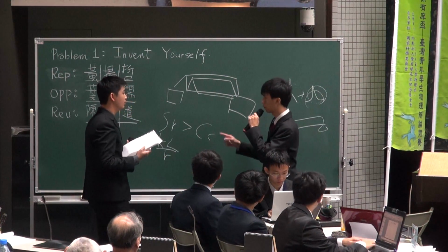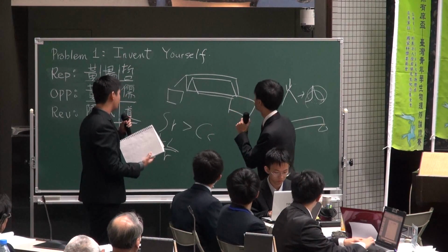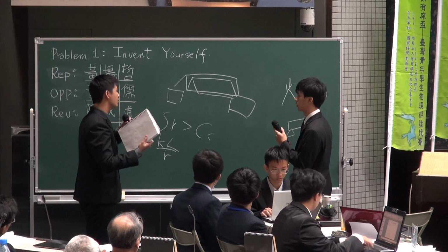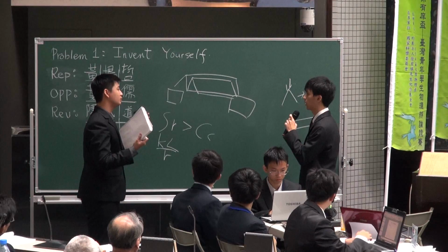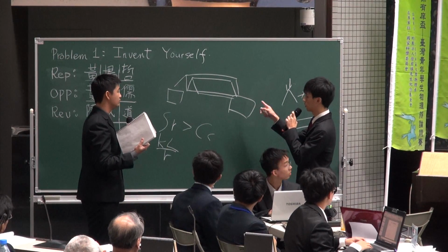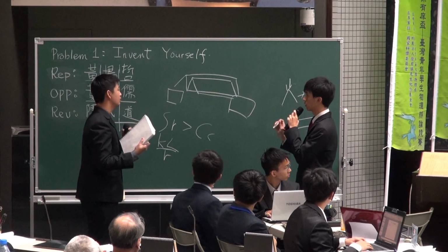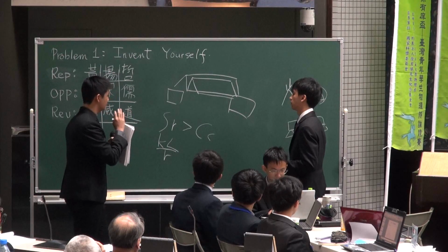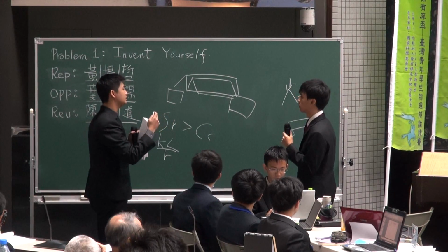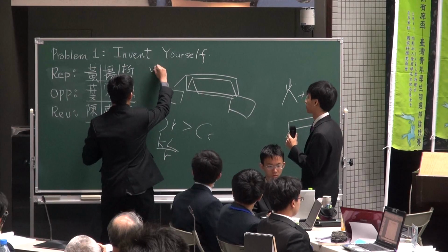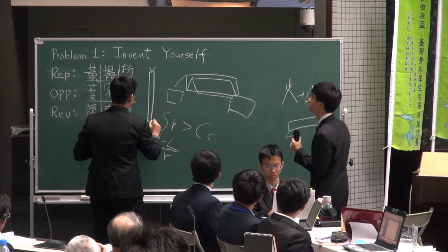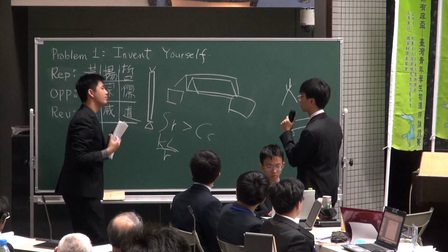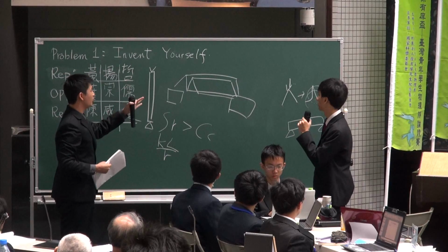Excuse me, you mean the end fix? Yes, because first there are two problems. When you use a long column, the end fixed situation needs to be specified. But in my experiment, the paper doesn't have the end fix. So your condition is that when you press the paper it will move. It's not a pin column. If this part cannot move but it can rotate, it's a pin situation. So what is your situation?